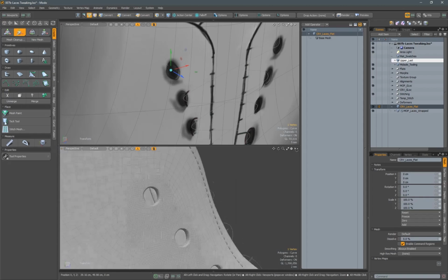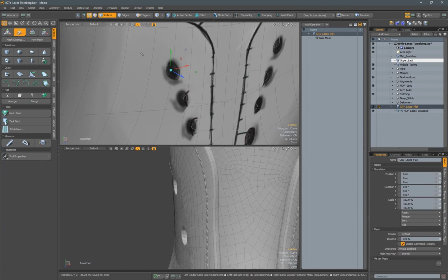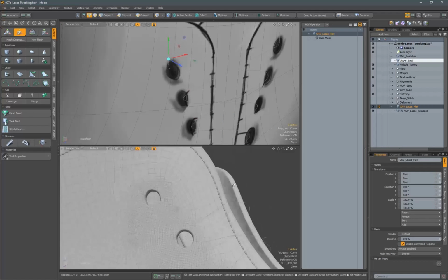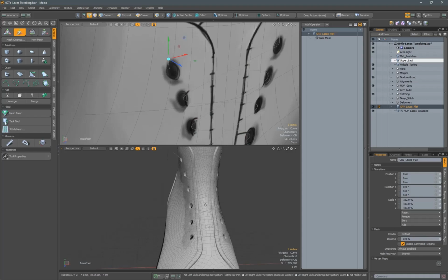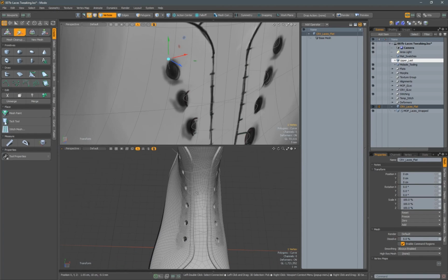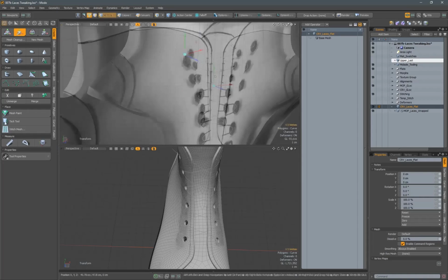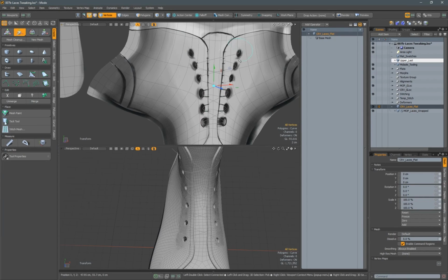And that should do it for that one. Oh, looks like that one's protruding through the shoe. There we go. So another thing that we want to do just on a global scale is each alternating overlapping lace will push one up and then one out. The easiest way to make that happen is to select one of these ends of the lace and then use the shift up arrow key to select all the way down to right there.